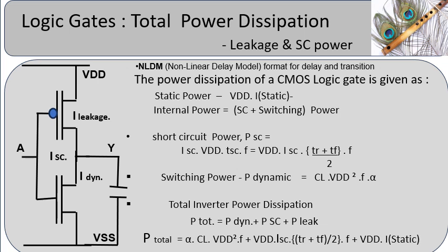Power dissipation in a CMOS inverter arises mainly during switching activity to charge and discharge the load capacitor. It can be broadly classified into three types as described below. Leakage power dissipation: a CMOS gate in a non-operating or static condition carries sub-threshold and gate oxide leakage currents that lead to static power dissipation.